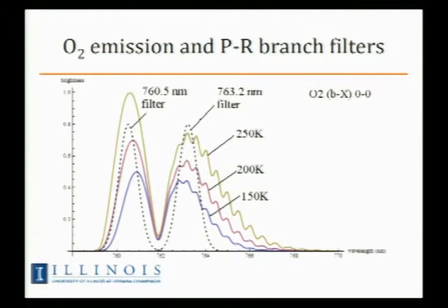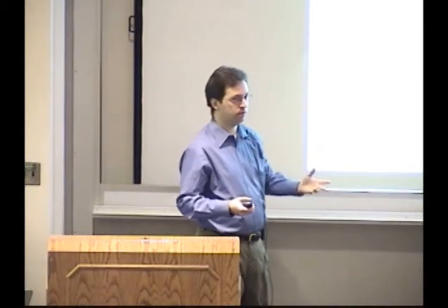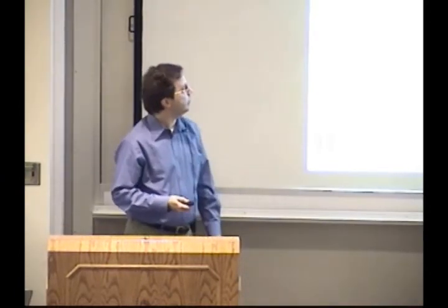So these black dotted lines show the transmission profile that we have envisioned for our filters. One engineering challenge of this is that these transmission profiles are temperature dependent. So the center band will shift to left and right based on the temperature of the filter itself. So we have to implement some little heaters to keep them at constant temperatures. This is a signal analysis for the PMT channels. There are 4 of them.